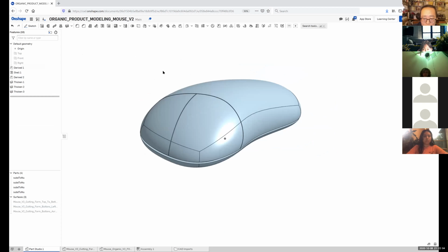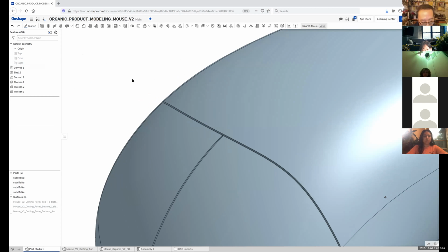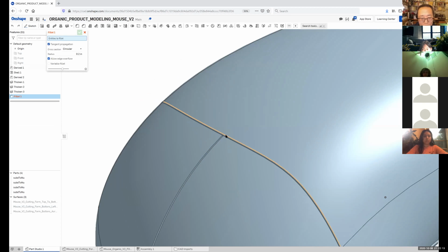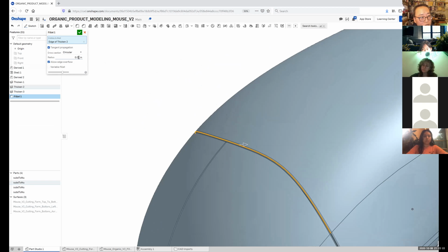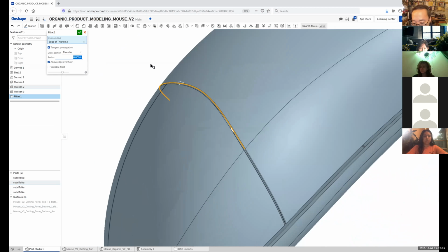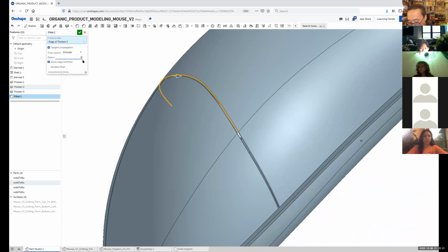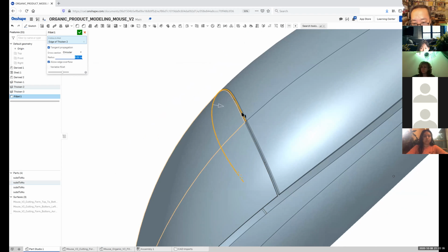And for cosmetic purposes, you can give some fillets to these things. Shift F is the fillet, which is also the same thing as this one. So let's do something like 0.01. That's like the thickness of this. Actually, let me check the thicken, 0.005? Would that be? Oh no, 0.01. Okay, not bad.